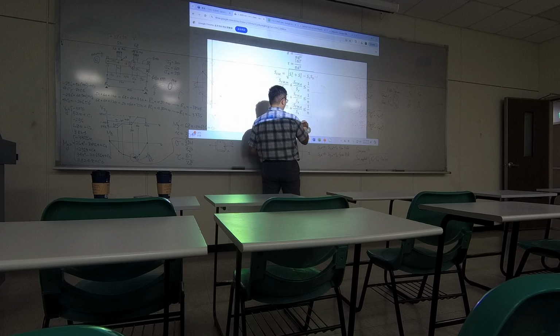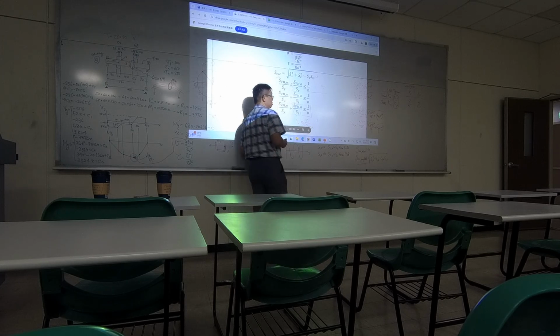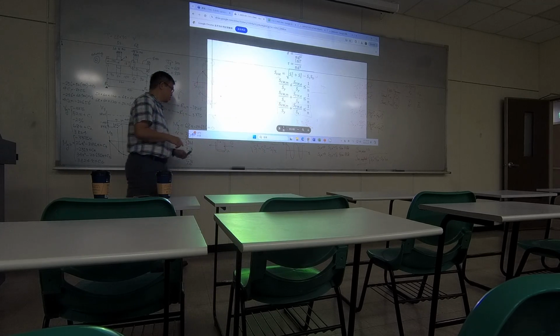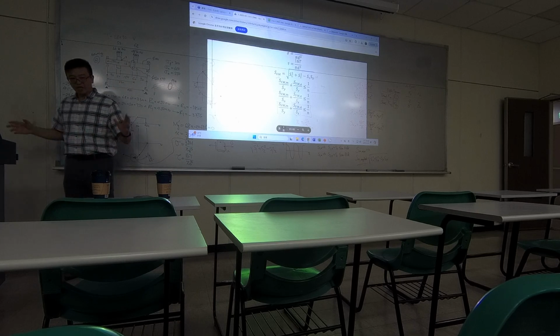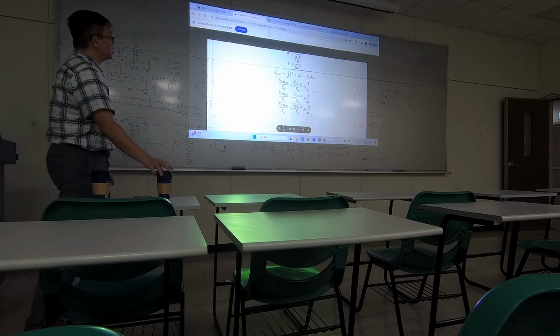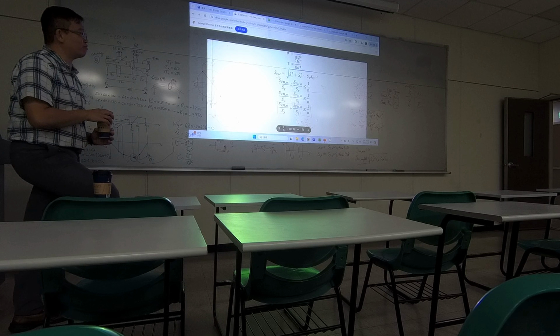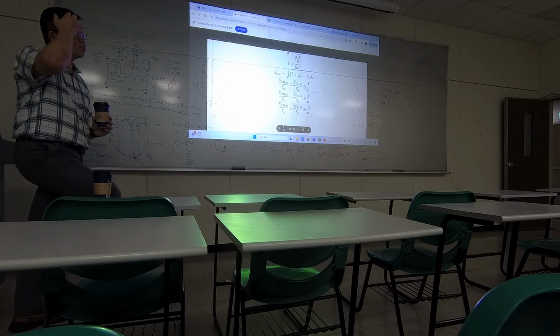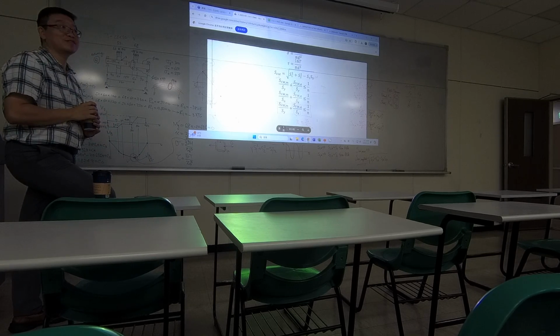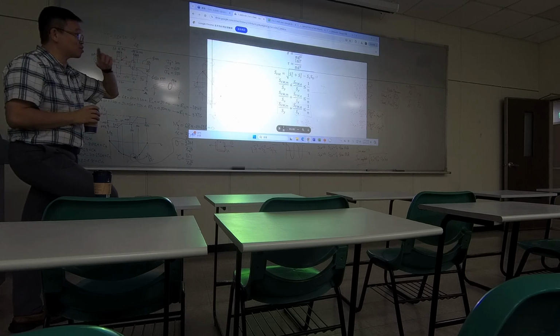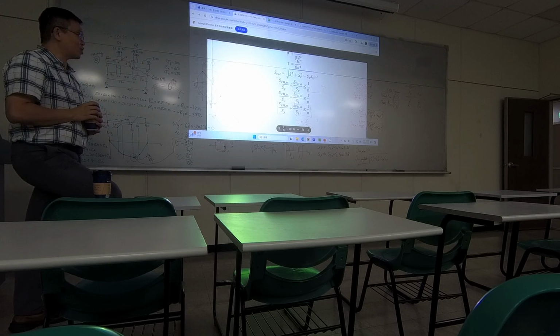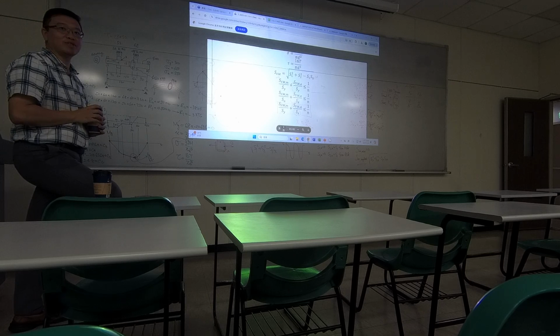So at the end, n will be smaller than St over S von Mises. That would be your answer. For this unique condition, the mean part of the von Mises equals 0. Okay? So that's how the solution can be determined.